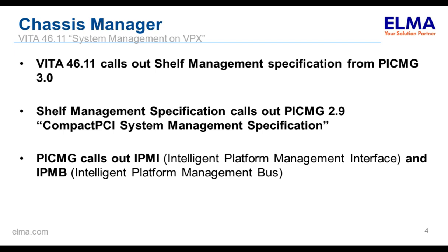And so the VITA 46.11 calls out the chassis management specification from PICMG 3.0, which is the ATCA specification. The shelf management specification from ATCA then also calls out the PICMG 2.0 compact PCI system management specification, and PICMG 2.9 then furthermore calls out IPMI, which is the Intelligent Platform Management Interface, as well as the IPMB, which is the Intelligent Platform Management Bus.